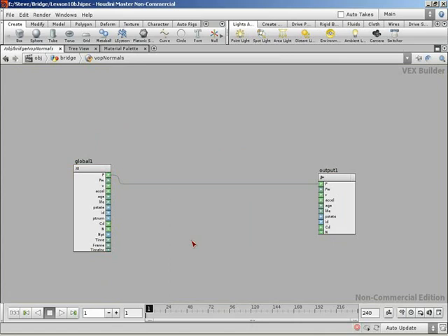Yeah. But we are going to be changing the normal, so we will be wiring something up to the normal. Okay. And the way we're going to do this, we're basically going to take the position of our current point and subtract the position of the previous point from that. It's going to give us a vector. With that vector, we'll normalize it just so it's 1 in length. No matter which direction it's pointing, it will be 1 in length, and we'll pump that out as the normal. That sounds good. So let's look at how we can access the previous point.